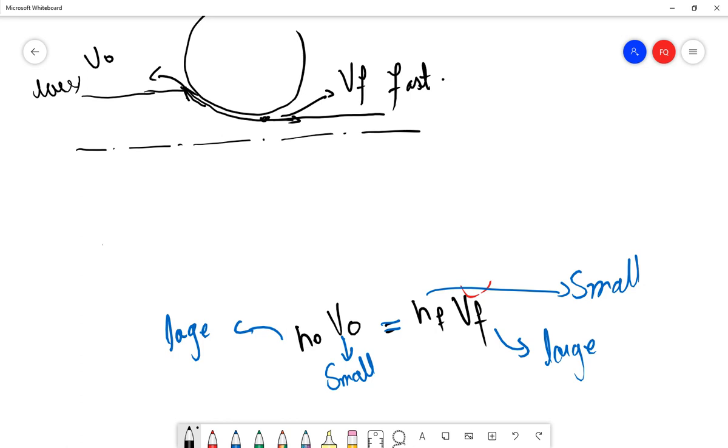Okay, and when this material is moving in slowly and this material is going out faster, what is happening is that the velocity is changing throughout this grab angle. If I plot it like this, alpha, so the velocity is fixed before this line, velocity is fixed after this line, but it is changing from this slow velocity to high velocity throughout this line. Is it clear?